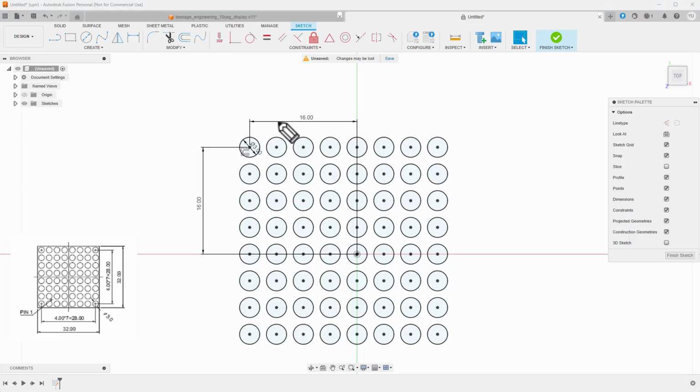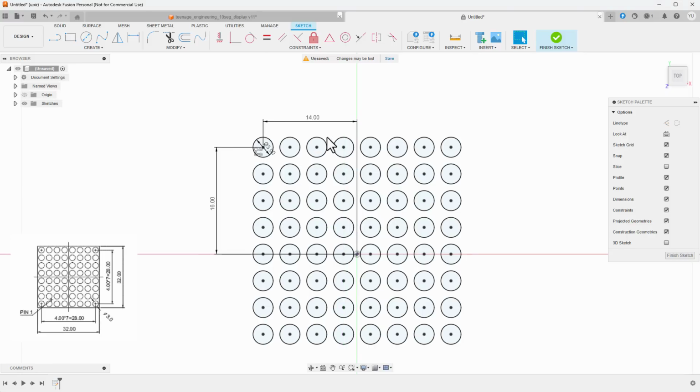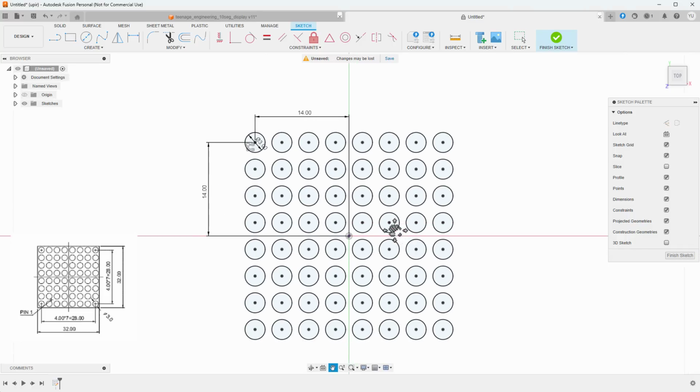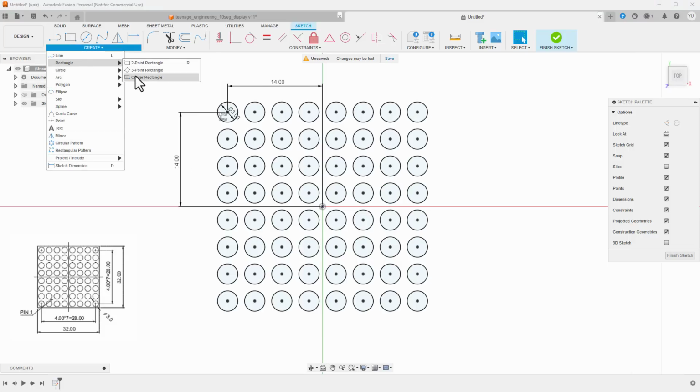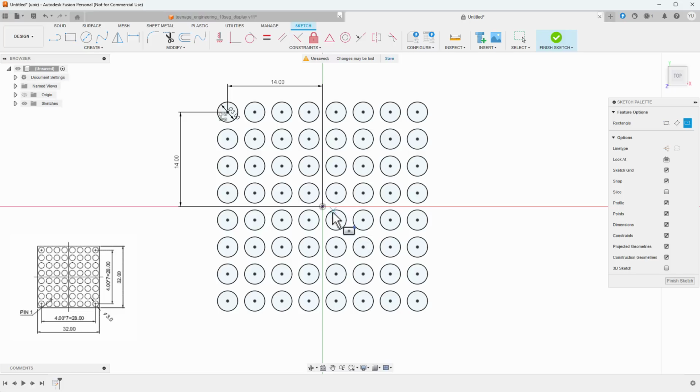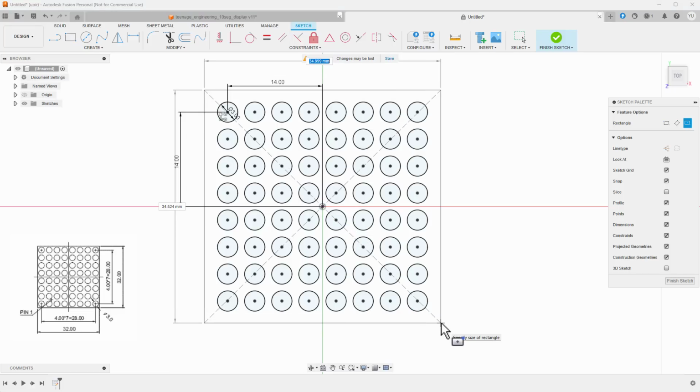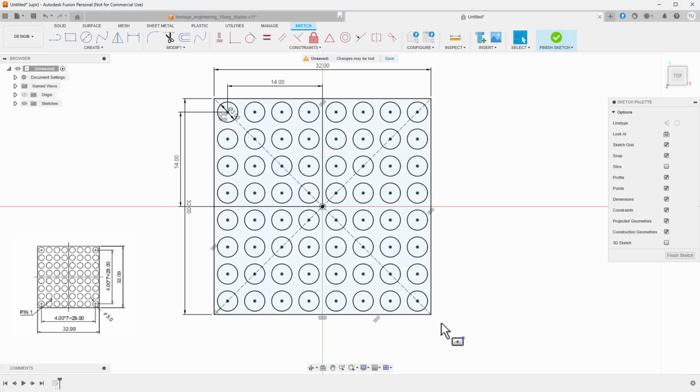And you can see that the X and Y spacing is not correct because the center should be in here, so offset by half of the spacing. Which means that the X position shouldn't be 4mm but only 3.5mm, and the same should be also for the Y position, so 3.5mm, and that should put all those LEDs into the center. Let's also visualize the outside by creating a new rectangle, and that will be this one, the center rectangle, and draw it from the center of the sketch, and the size should be 32 × 32mm.